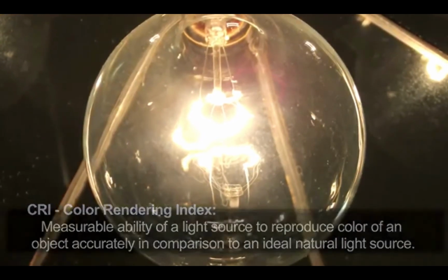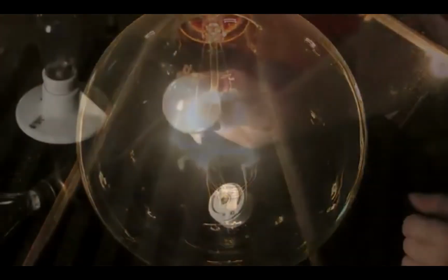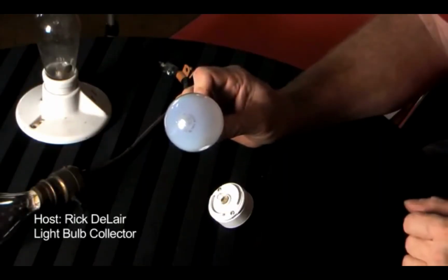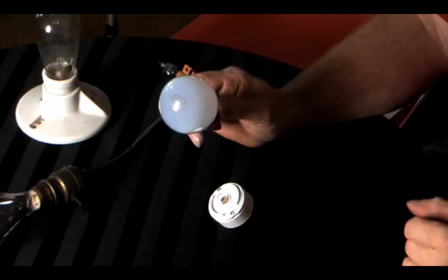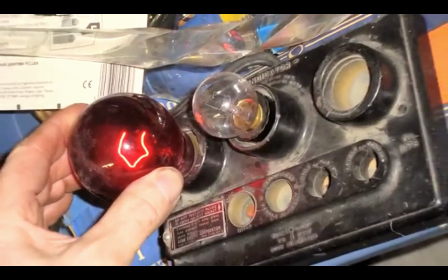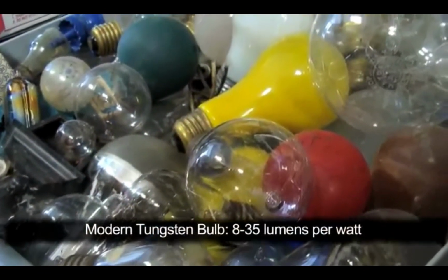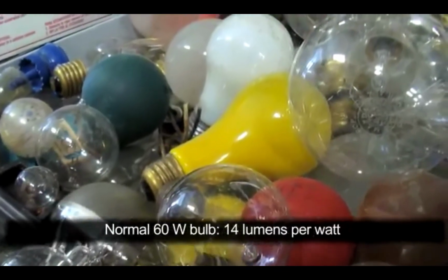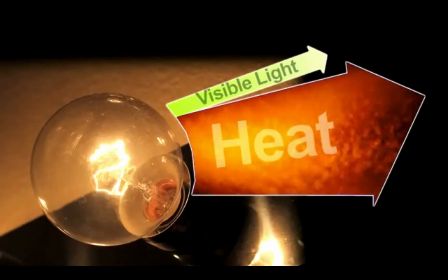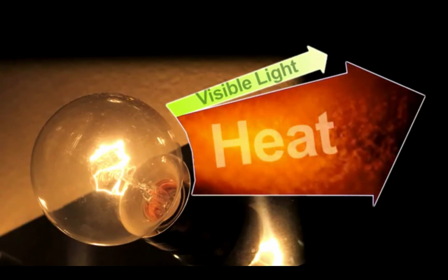They don't need any auxiliary gear, which means you can plug them straight into household current and run them. You don't need a ballast, so there's no losses from a ballast. And they have a decent life. Some of them are longer life than others, but most are about 1,000 hours. The disadvantages are they're not the most efficient light source there is. In fact, only about maybe 10% of the energy makes light, and the rest makes heat.